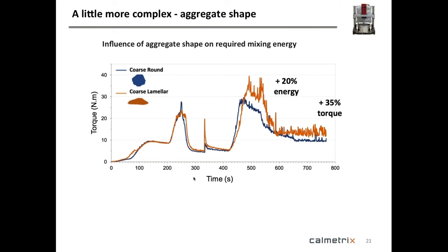So here we chose to look at something that's a little more esoteric. We said, well, why don't we look at this mix with two types of aggregates? So we could have the same exact mix with aggregates that are a little rounder in shape. As you see here, the blue ones are a little rounder in shape. So they were selected to be rounder in shape. They were selected to be similar composition, similar everything, similar density, similar particle size distribution, but they had a different sphericity. This was actually a quite extensive study that was done, somewhat complicated.